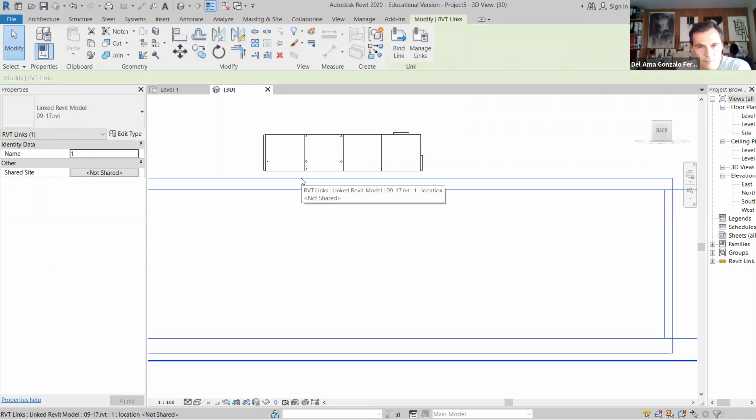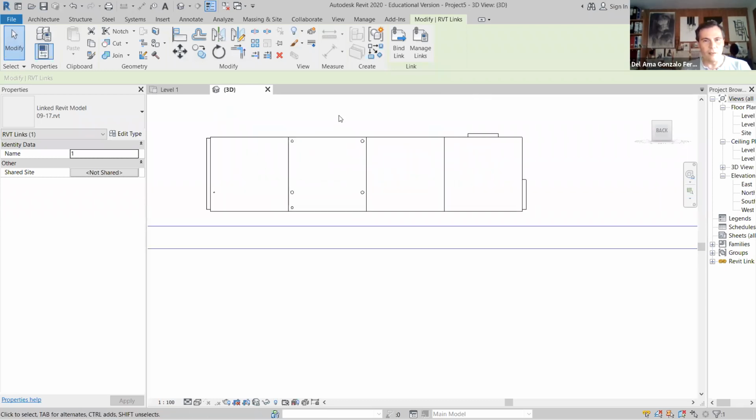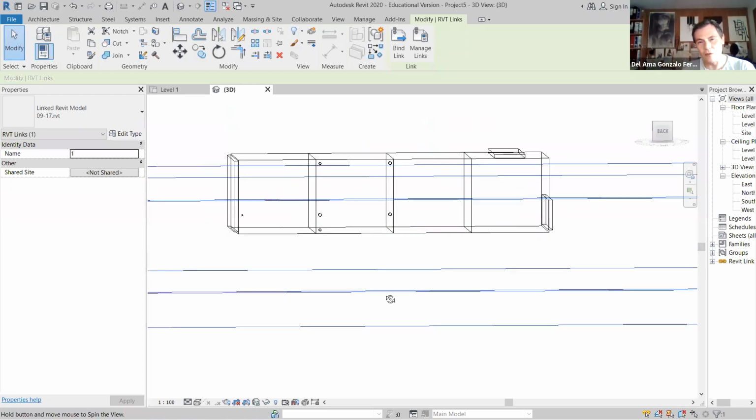Okay, so it was on level 2, but it has to be above the slab. Usually this is not just on the slab because it vibrates and makes a lot of noise. So we need some legs, and we need something for placing this because it weighs tons. So we need a structural reinforcement. Knowing where these elements are is important even from the structural point of view. So we cannot have a building and say, okay, where do I place the air handling unit? There, boom, because the building will collapse. So we need to know beforehand where to place all this stuff.